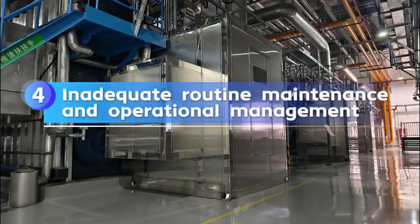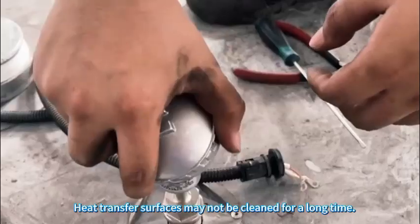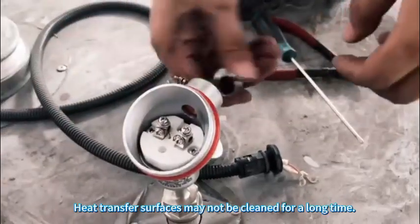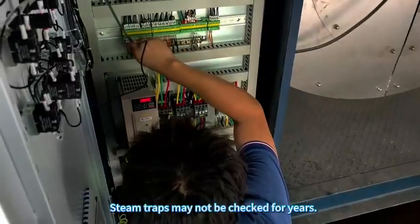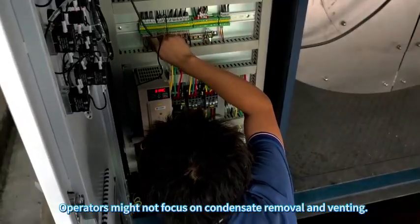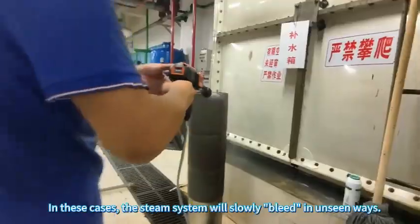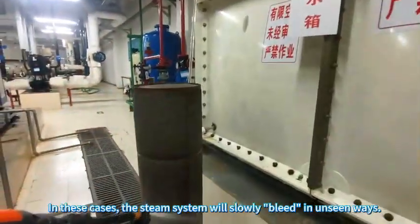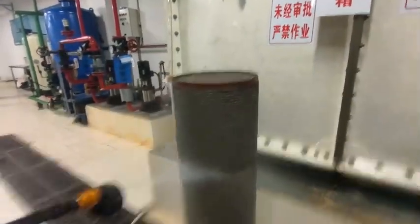Inadequate routine maintenance and operational management. Heat transfer surfaces may not be cleaned for a long time. Blowdown might be done just by experience. Steam traps may not be checked for years. Operators might not focus on condensate removal and venting. In these cases, the steam system will slowly bleed in unseen ways. It might seem like production can continue, but energy use and failure costs are quietly rising.